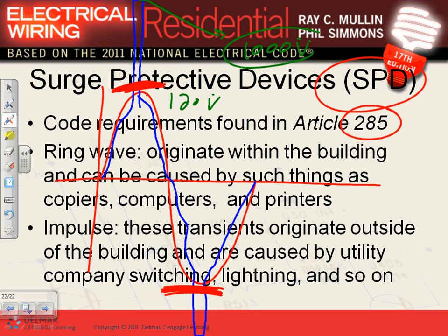They can come as a device, guys. You plug them in here. If there's lightning protection in residential, it's supposed to protect your plasma TV and your computers and so forth. Any question, guys, about SPD? In residential, it's not code, it's recommended. Engineering-wise, when we move into commercial buildings, we specify them at the service. Every commercial building service, we specify a surge protective device right at the service. In residential, we don't specify them. It's recommended to have a receptacle.